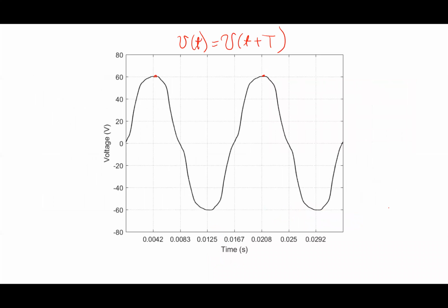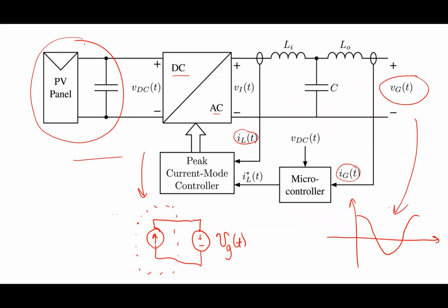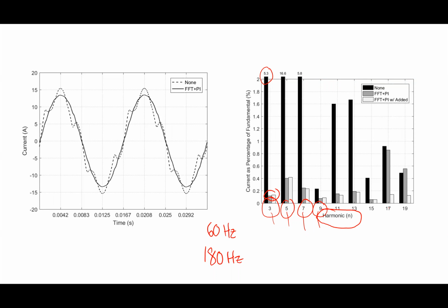If you look at what goes on in my microcontroller, it actually has a controller at each of those harmonic frequencies. So it's got to do calculations to figure out what the amplitude of the current is at each of those harmonic frequencies, and it uses the techniques we'll talk about here. Then I have a control algorithm that makes sure the amplitudes get to a desired level, which is very close to 0 for the harmonics. A lot of details there, but it's useful stuff.